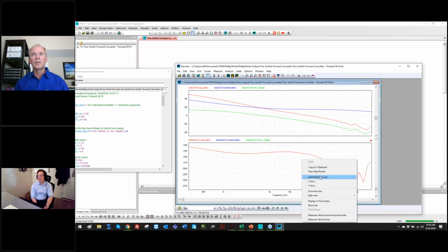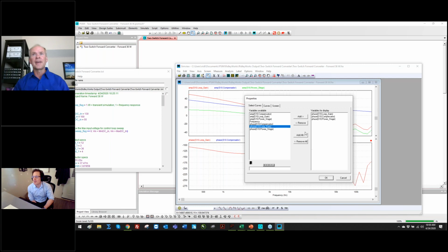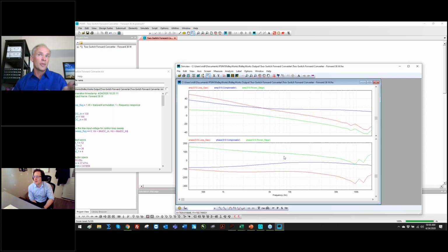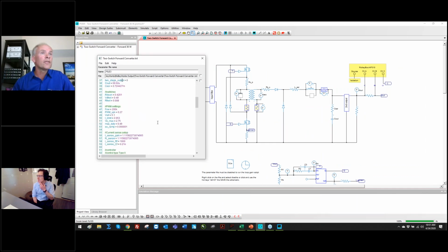Sometimes this doesn't plot, Albert. Yeah, let's check that. I ask it to plot the same thing again. And it brings them all in. They're easy enough to fix. Here we go. Here's our loop gain, crossing over somewhere near 20 kilohertz. Here's the loop phase, which you'll find corresponds to exactly what you got inside RidleyWorks. So we're now reproducing the loop inside Psim, and it took 4 seconds to do this. And I can't remember if we've got proximity models going here. Yeah, that should be the flag. We're not actually running the proximity models, but you could.